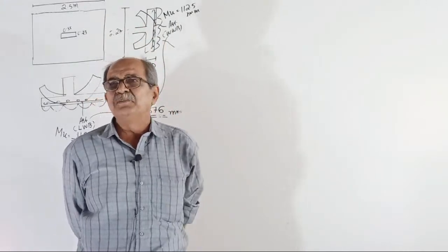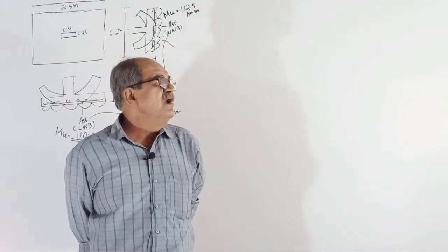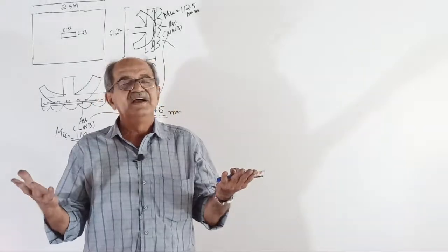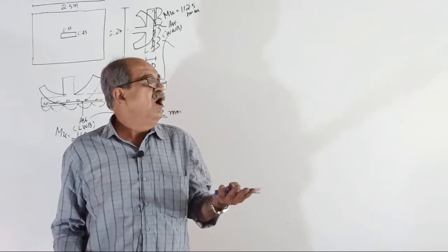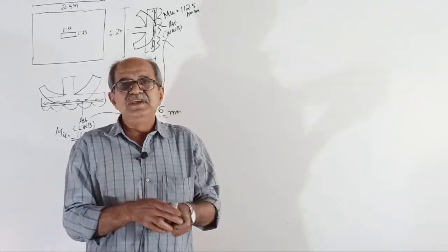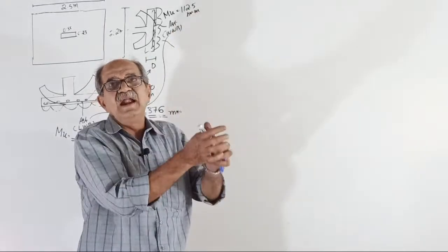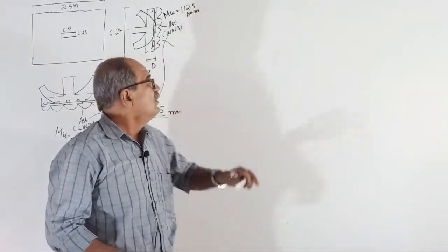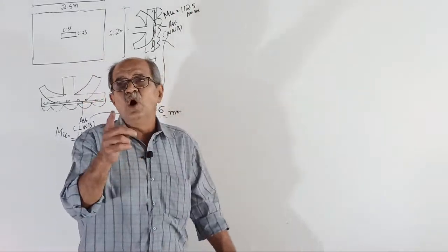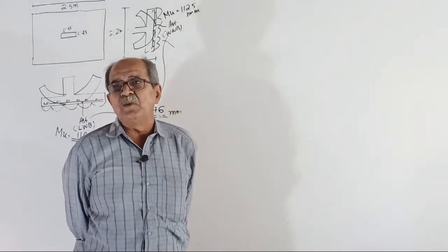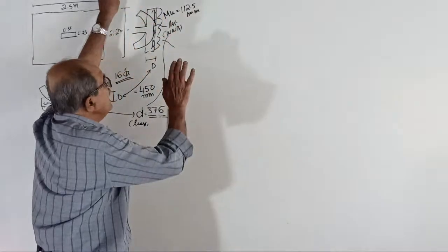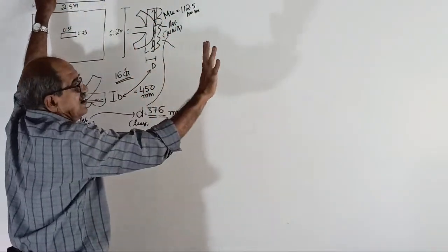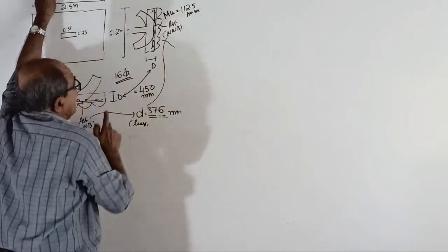See, understanding is important. That shear I will call one-way shear, or usual shear. Or still more easier, this is punching, that is diagonal tension crack. I will tell once again later. For checking that one, you should know what tension steel is provided. Therefore, for the time being, take the footing. Punching I have taken care of. Bending moment I got.